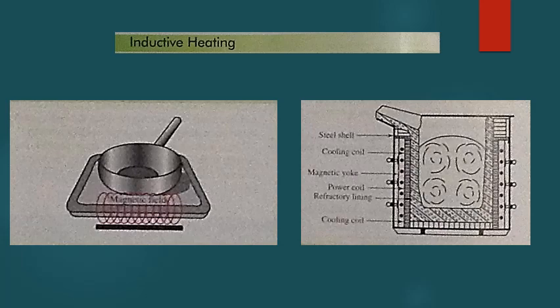To move on to a quick interlude for this chapter dealing with inductance, inductive heating. An iron or steel part inside an energized coil produces a magnetism as well as heat. This heating effect is caused by hysteresis and eddy currents generated by the magnetic field. The amount of heat produced is directly related to the intensity of the magnetic field and the frequency of the applied AC, or alternating current.